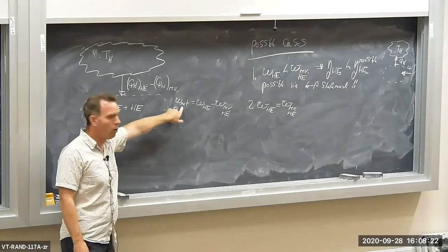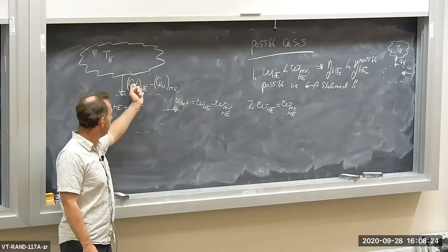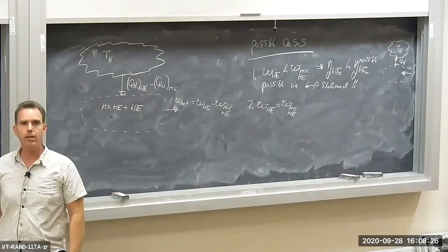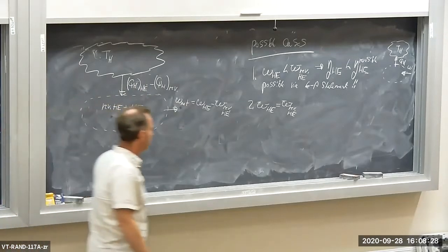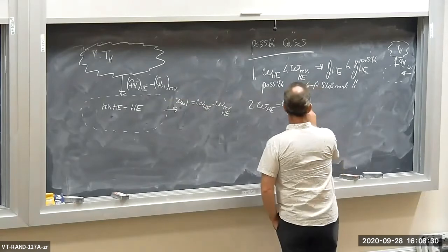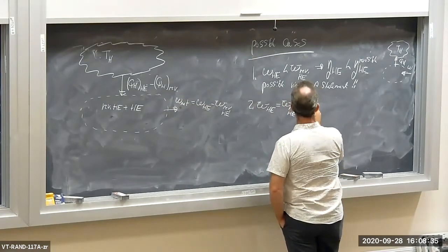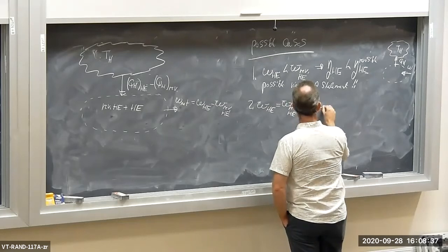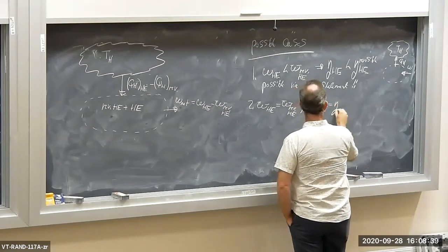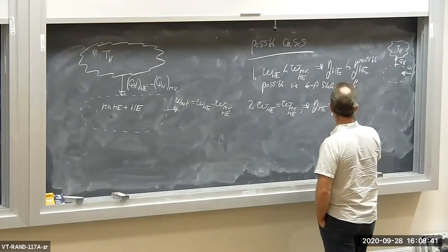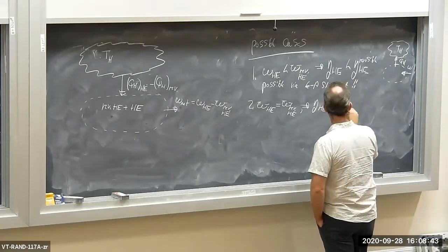It produces no work over the cycle. Therefore, it cannot extract any heat over the cycle. So this implies the works are the same. This means the efficiencies are the same. The reversible heat engine and the heat engine have the same efficiencies.